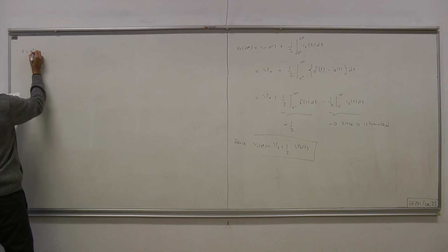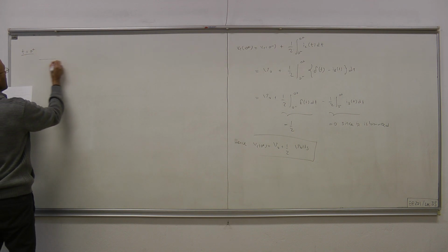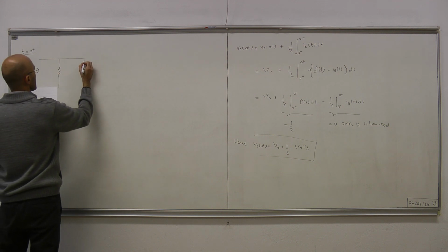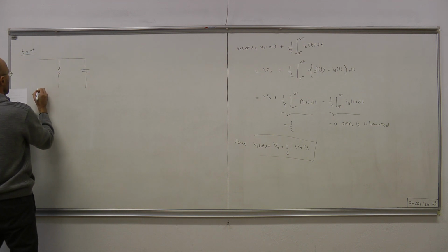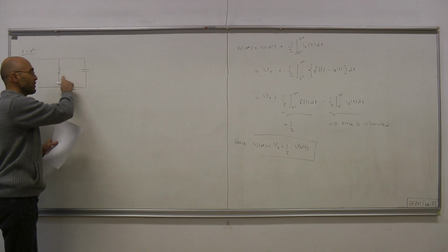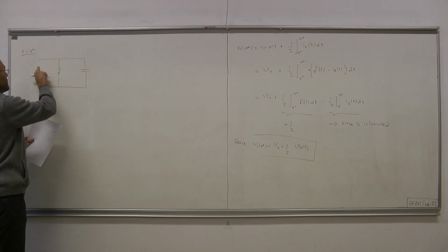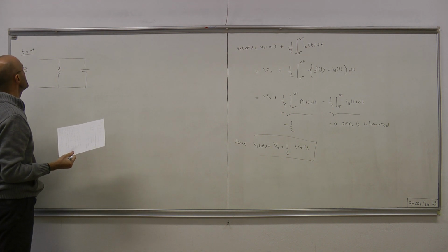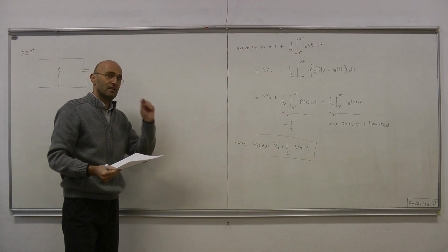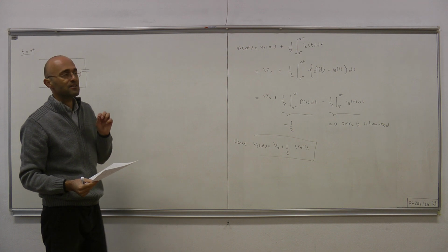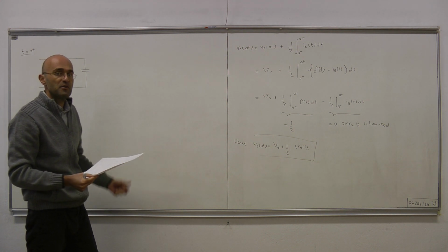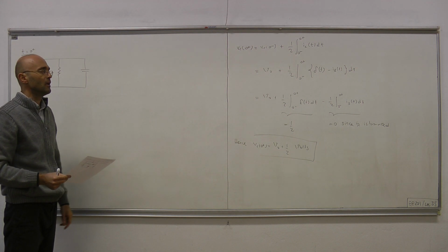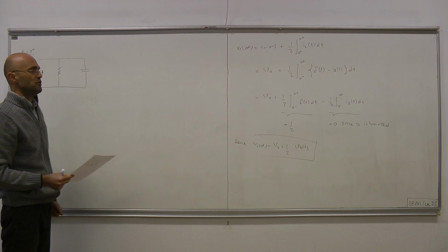Let's figure out the remaining quantities that you were asked. At t equals 0+, we have the resistor, the capacitor, and the impulsive current source. Now, the impulsive current source does the interesting stuff only throughout the interval between 0- and 0+. Once you're to the left or right of that interval, then it's just 0.